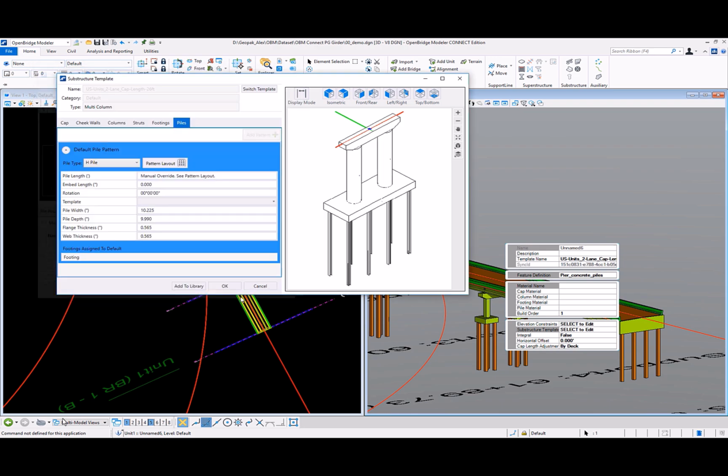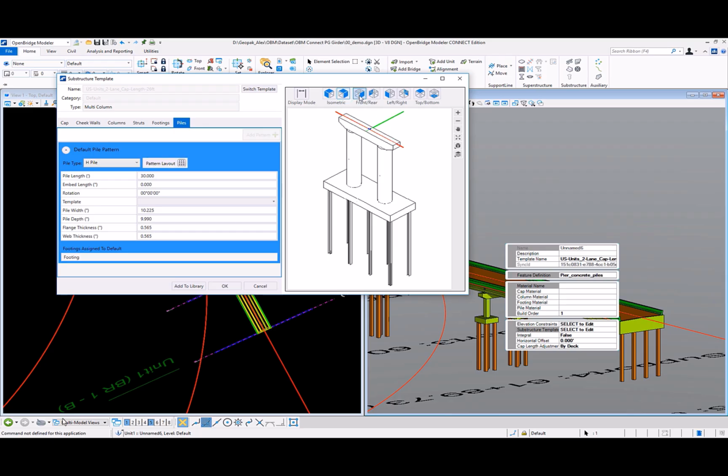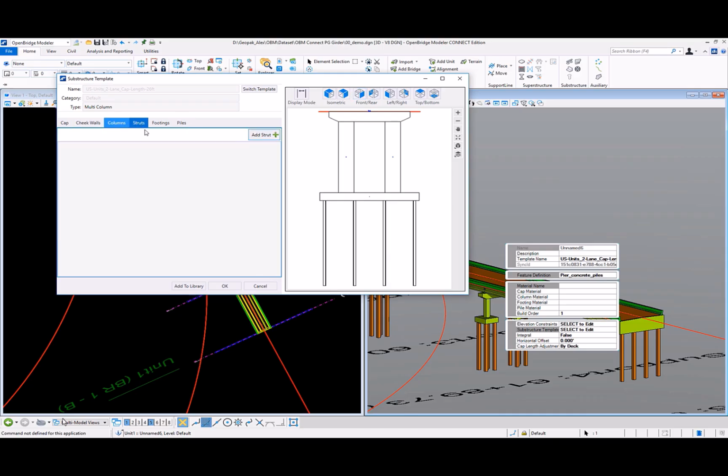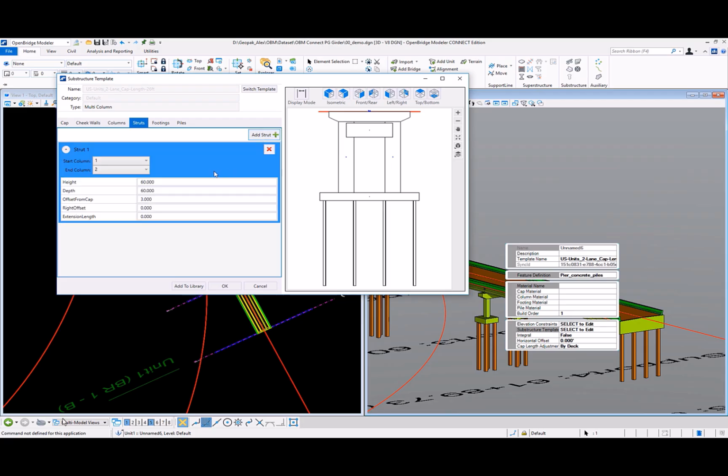Specify distance, and so we'll just generate that. If it looks good, then I just save it to my library or just place it and make it part of my model as well. At that time, just to remind you, when we place that element from the library, the element is disconnected from the library, so it just became its own element.